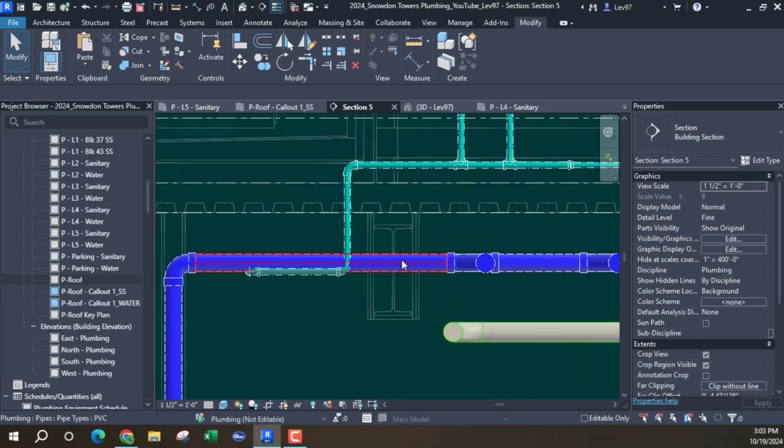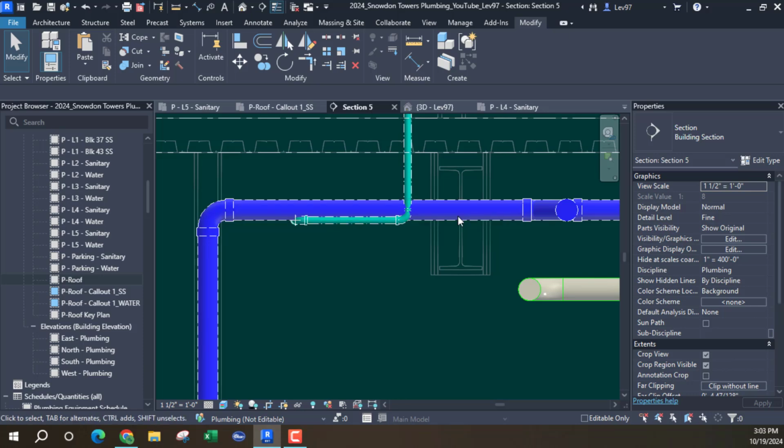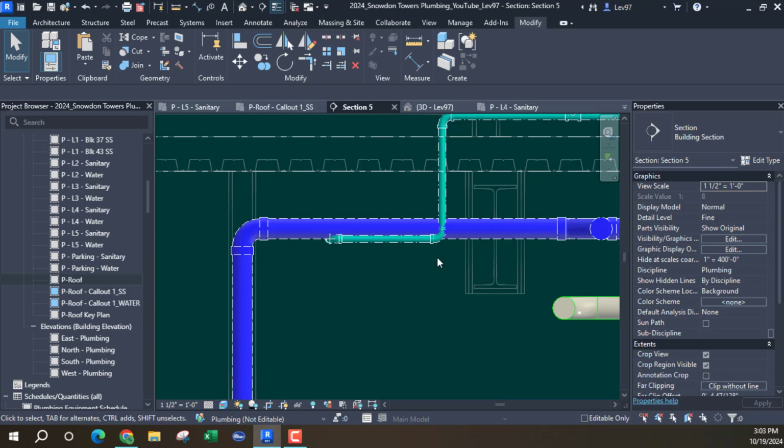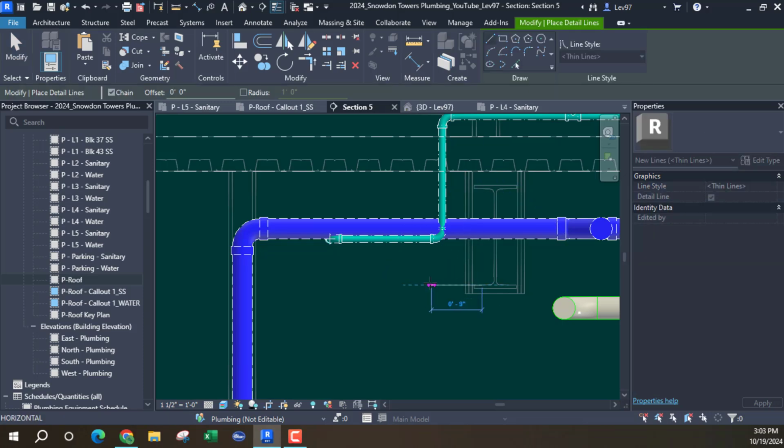So I think that we're going to have to do something with this pipe, even though the contractor is going to put it at 1/3. I know that 5.33 on both ends, and then I'm going to do a detail line because the pipe has to go within the middle third of the beam. That's the zone. I'm going to type 0 space 5.33. Okay.